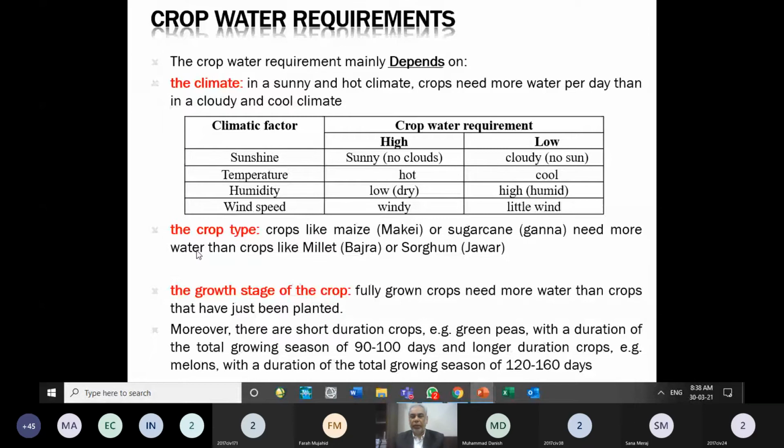The second factor which affects the crop water requirement, of course, obviously, is the climatic condition. Climate includes the temperature, the sunshine hours, wind, and humidity. So these things control evaporation, evapotranspiration, and crop water requirement. It's because in hydrology we have told you evaporation from a certain area is dependent upon climatic conditions, and all these four things were informed to you.